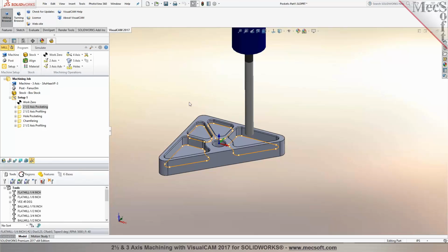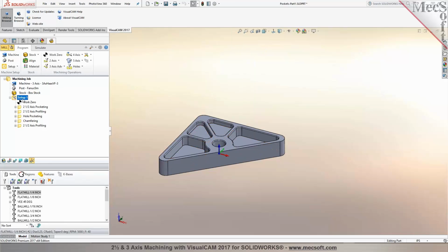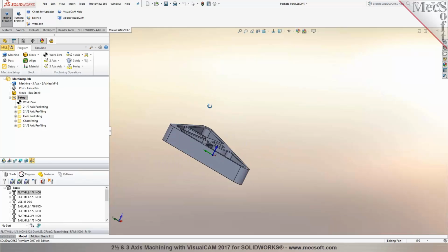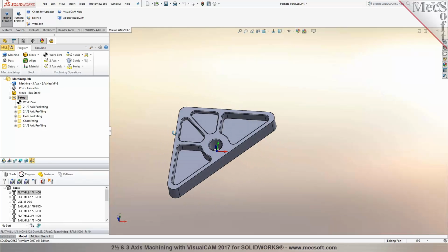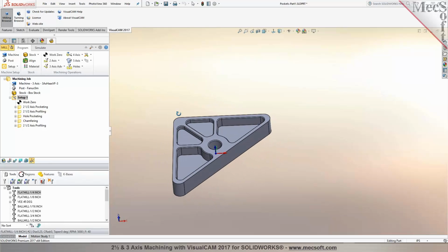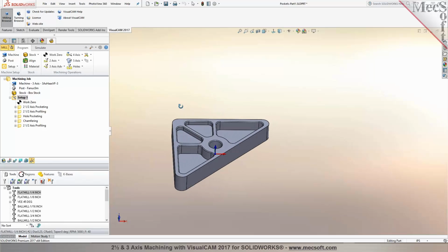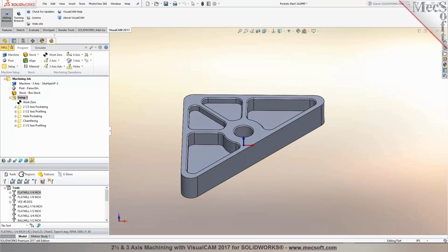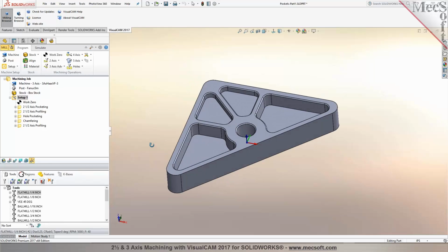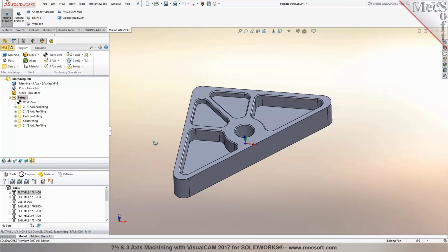And at that point, I need to give some indicative information to him, such as which point I have already defined as the reference point, how I am planning to fix the part on the machine, and what is the order of the tools in the tool changer, and which tools are defined on which tool number, something like this.